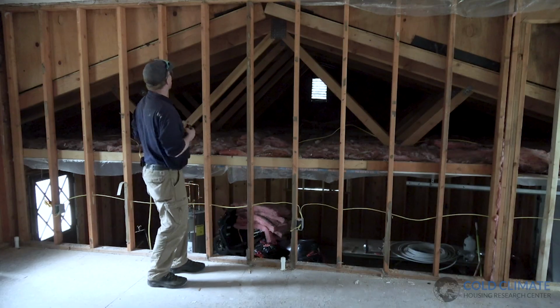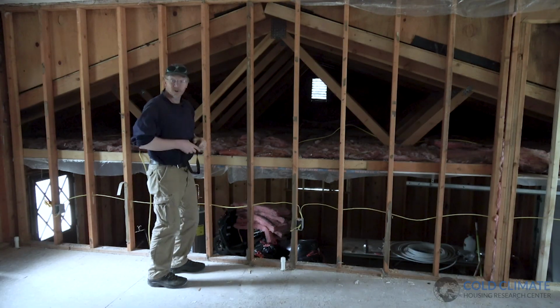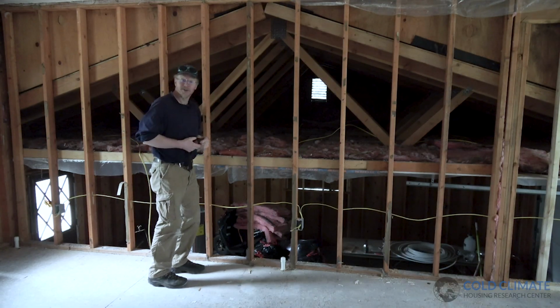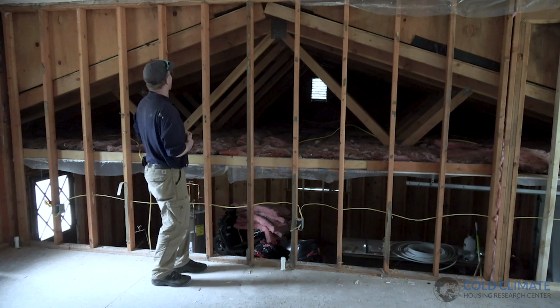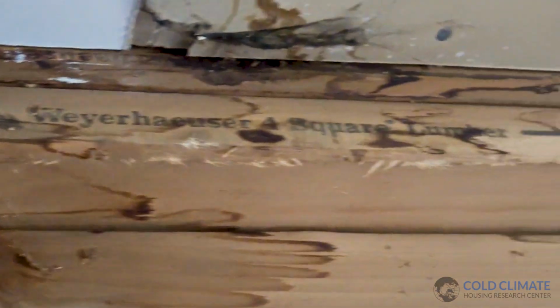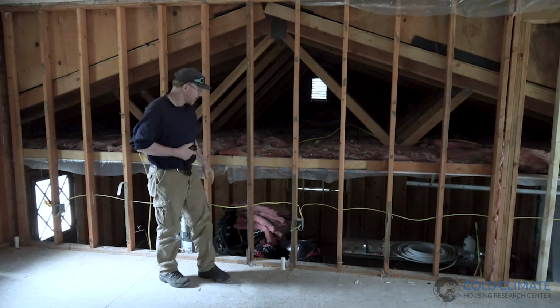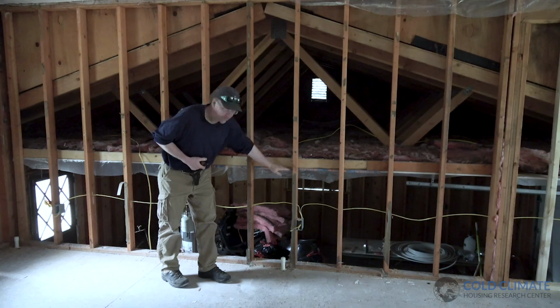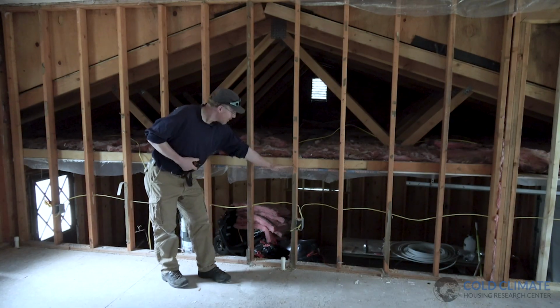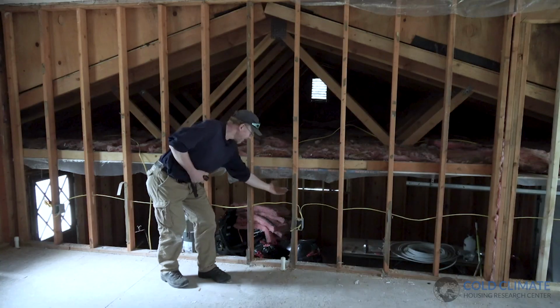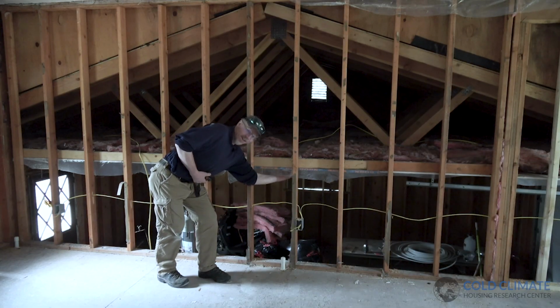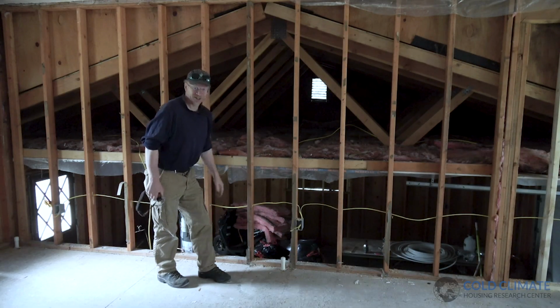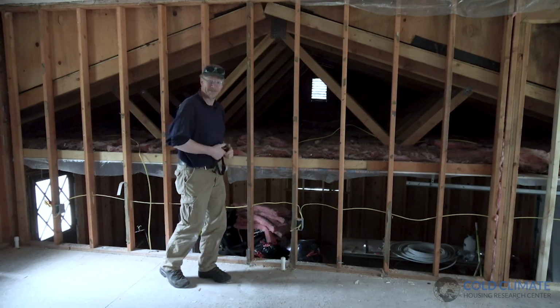And you know, I think this house got lucky. It's an older home. It's obviously an energy pig with lots of air leakage. And in this case, that means this place dried out pretty well. I don't see that as an excuse that we should build leakier homes. I see it more that we have to address these thermal bypass problems and continue our thermal and pressure boundaries right through where we have continuity between whatever heated structure is attached on one side to the heated structure on the other side. So let's get started.